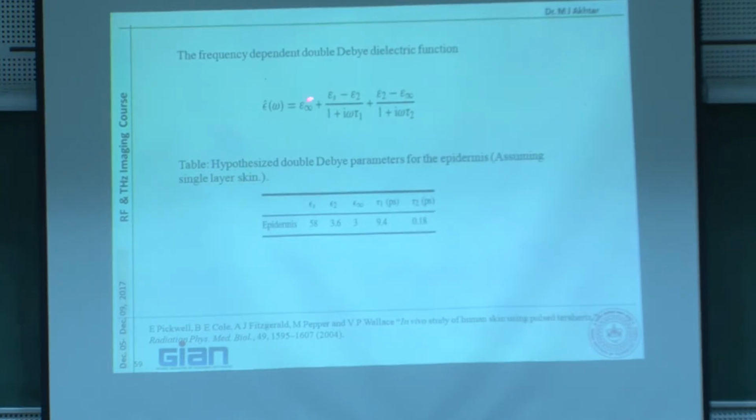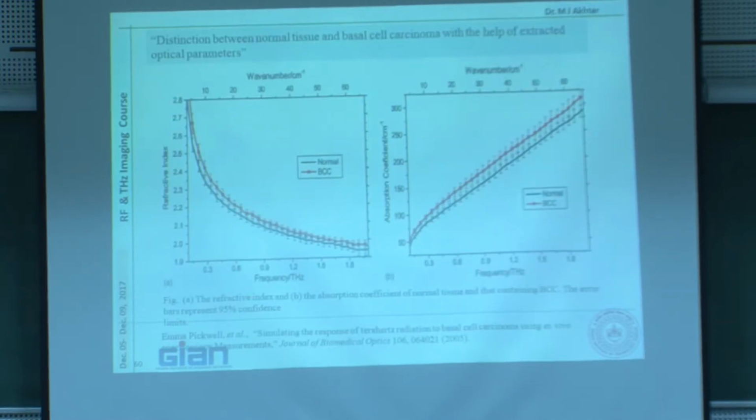If you just measure at high frequency and low frequency, the F infinity means, for example, let's say you measure at 1 terahertz and you measure at megahertz. By these two things you can make a model and obtain tau 1 and tau 2, so that the epidermis, which is actually the most outer skin, you can obtain its property over this. People have done this. So, you can use this data to obtain a skin model over a wide band. Once you do this, then you can try to obtain the effective index as a function of frequency.